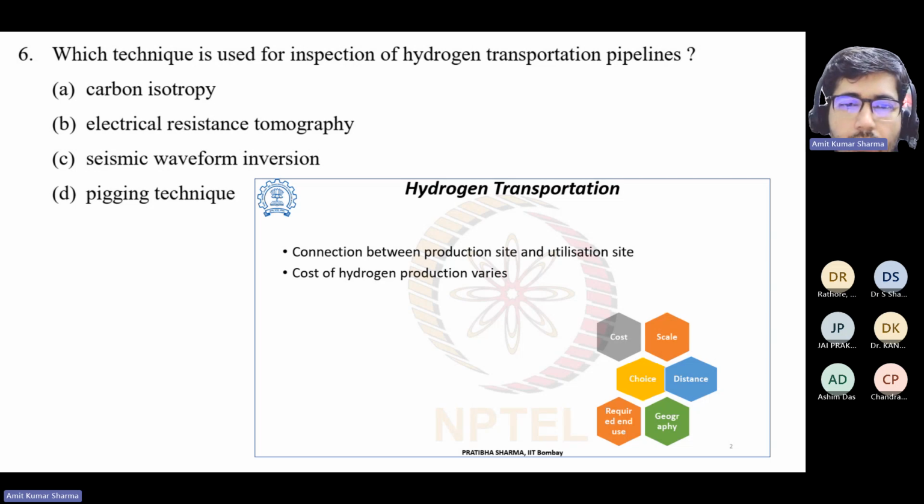It's not only at the beginning. It is a routine process. Every company has a document that they need to fill in, saying we have done this pigging on this date, because they have to maintain their records also. As per ISO also, you need to do the pigging.